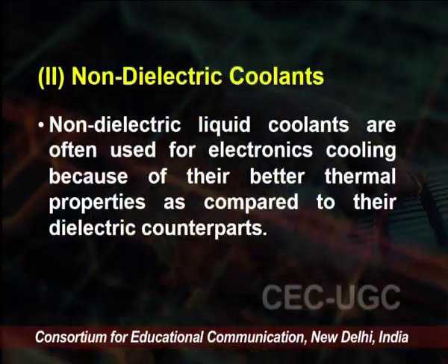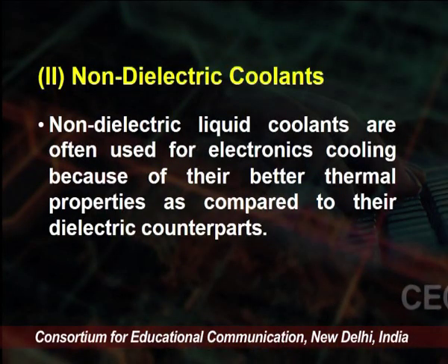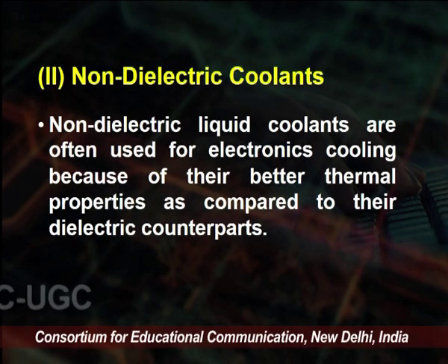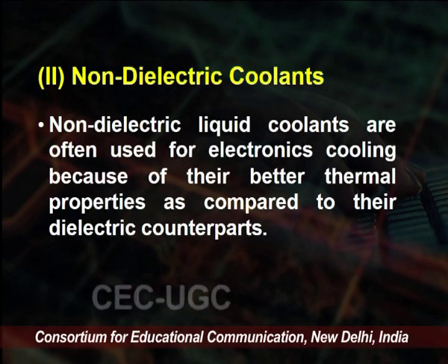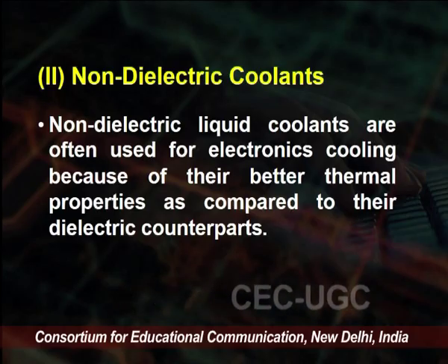Non-dielectric liquid coolants are often used for electronic cooling because of their better thermal properties as compared to the dielectric counterparts. They are normally aqueous solutions and thus exhibit high thermal conductivity and high heat capacity as well as relatively low viscosity.